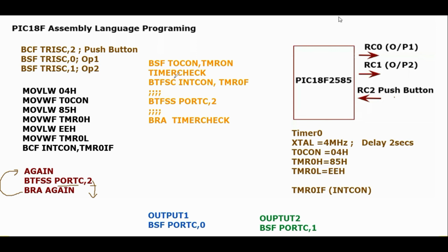So what I'm doing here is testing whether your timer is not expired yet. If it is not, then skip this line. And what is this line? We are testing if it is still pressed or not. If it is pressed, then skip this code and go back, so it will loop back, right? So basically we are testing two things: if the timer is still on, that means 2 seconds have not passed, and the switch is still pressed, right?